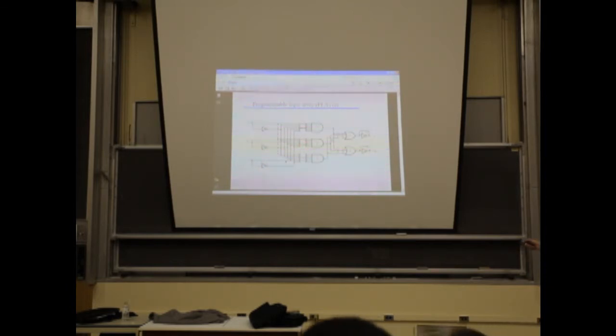So by choosing the right ones, by burning them, like putting the cross on a specific line of them, when you put a cross in our course notes, it's like creating a link or a fuse between the two. Just think of a fuse there that you will activate if you would like that specific literal to be pronounced in the product term. Okay? So we have them.